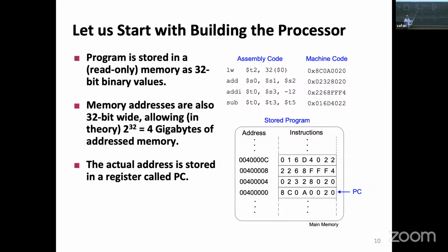So program counter, clock starts. Clock comes. So that's one cycle that we have to finish, all in one clock cycle. This is why we call it a single cycle architecture. And regardless of what the operation is, hopefully the ALU will be able to decode all the 64 different R-type operations. We are actually good. But now let's do something evil. We want to bring some data into our register file. We want to load a word.